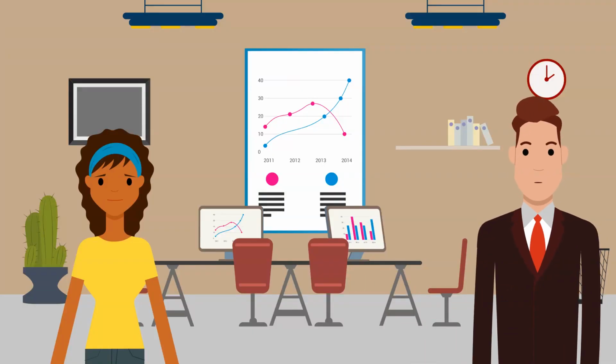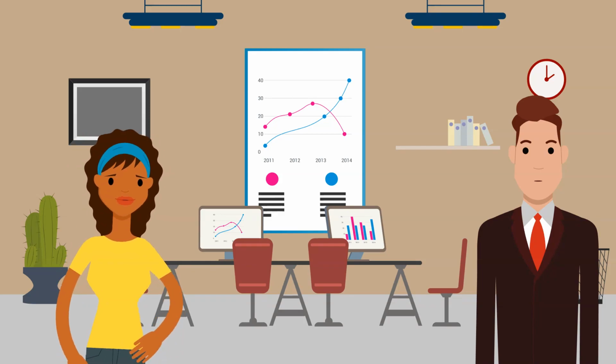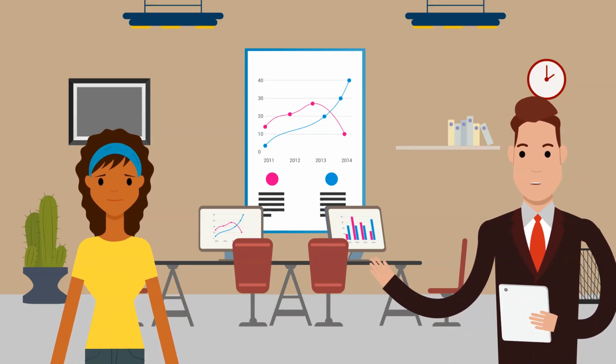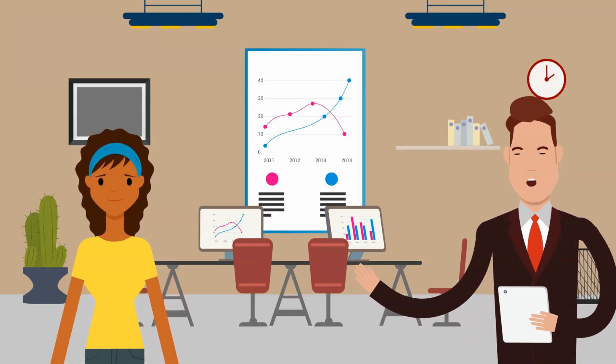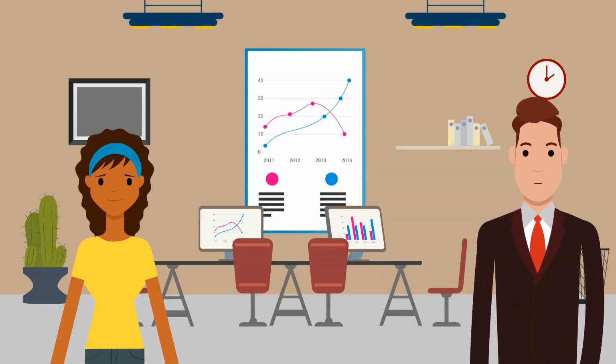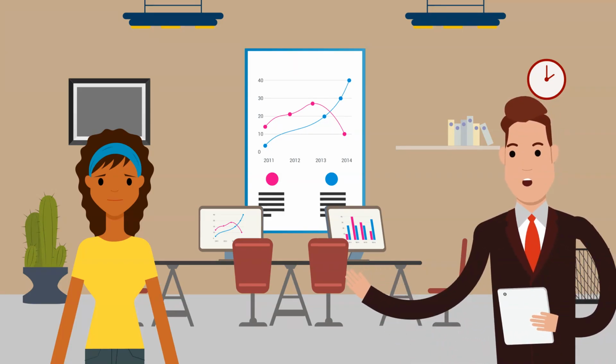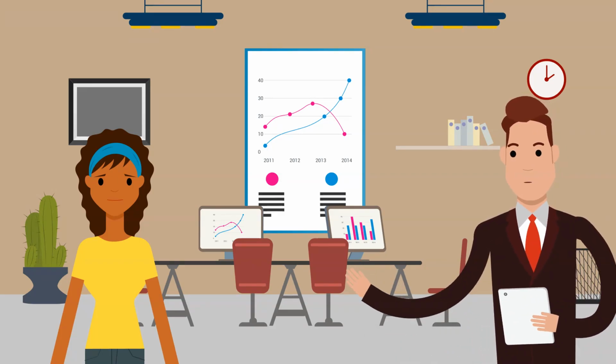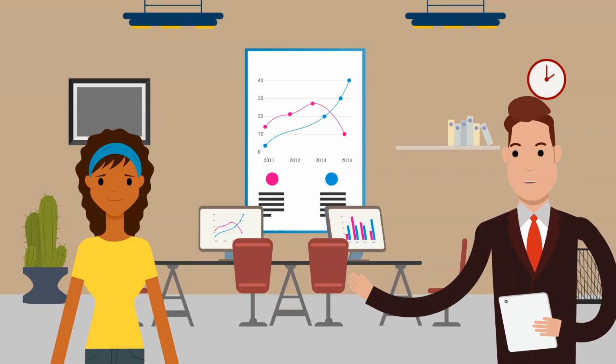Isn't that cool? That is really cool, but I have a question. What does the data look like and where does a user get it? There are 3 data templates that Layout IQ supports for calculating flow in a layout. The method you choose to model flow in your layout depends on the data formats you have. The simplest modeling method is called from-to trips. It is used if you have a simple count of how many trips are made between locations.